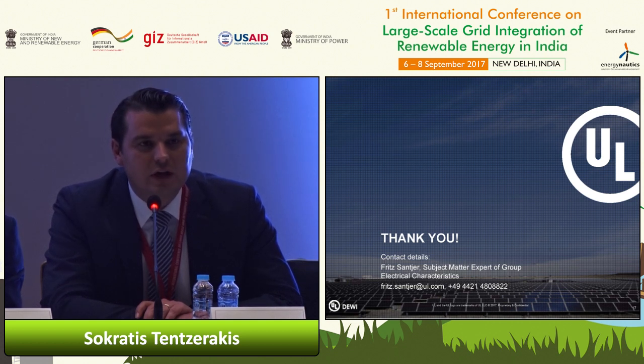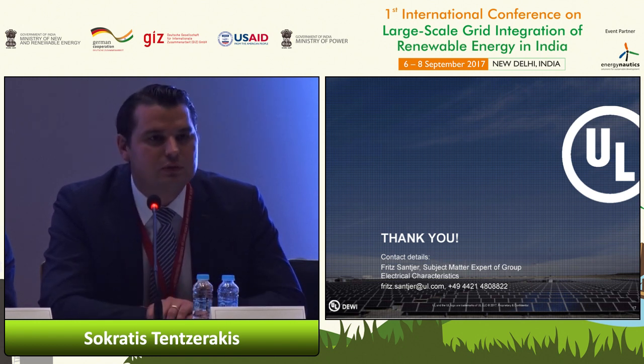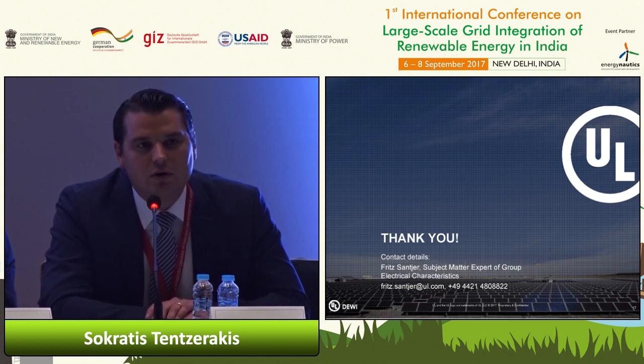So they provide a signal, and then after this signal has been given, there must be a ramping of the pre-qualified power generator. However, this is not certified by the certification office, who assess, for example, also the electric characteristics of wind turbines or solar power plants. So this is a totally different measurement campaign, and is subject to all requirements from the grid code itself.